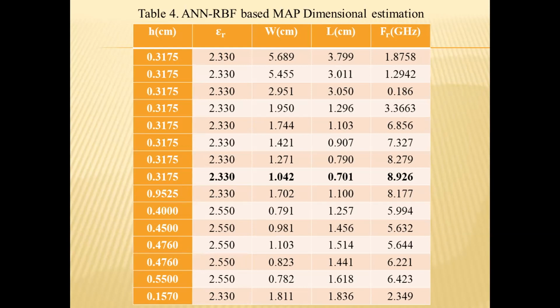So considering the key features of ANN-based method like local minima, and convergence, in this paper we applied an adaptive genetic algorithm ANN for learning enhancement and dynamic weight estimation. For microstrip patch antenna synthesis, we maintained 3 input neurons, 6 hidden neurons, while 2 neurons were defined as output to obtain 2 patch dimensional parameter width and length. The simulated result obtained by AGA-ANN model is given in table 5.